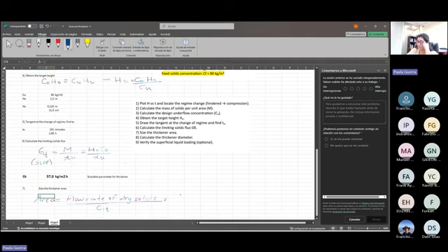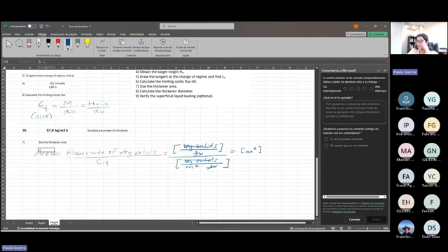And if we analyze this dimensionally, this is going to be kilograms of solids over time divided by kilograms of solids over square meter over time. So time gets cancelled out, the solid mass gets cancelled out, and we finally end up with the solids area. Now, we have to calculate the flow rate of solids in order to do this. Flow rate of solids.